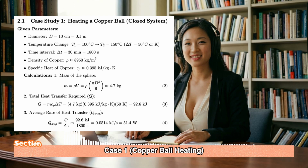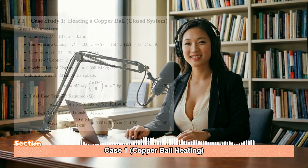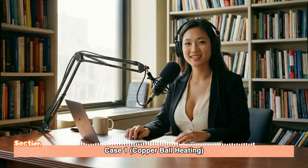Precisely. That 51.4 watts is the average power that the heating element has to supply continuously for half an hour. And without that heat transfer rate calculation, an engineer would just know they needed 92.6 kilojoules. Right. They wouldn't know if they needed a tiny battery or a massive industrial heater to achieve it in the time they want. That makes the distinction crystal clear.